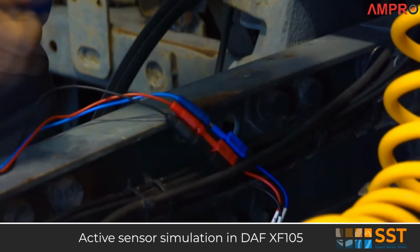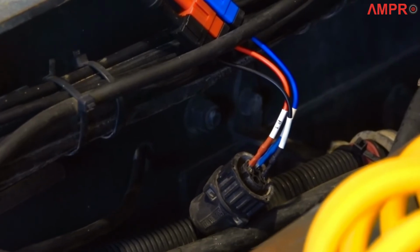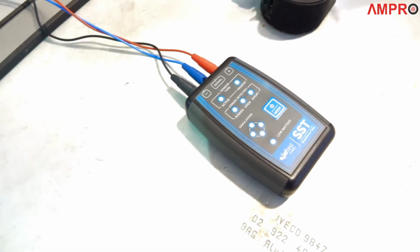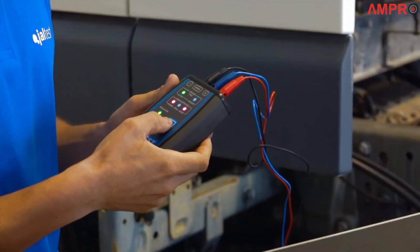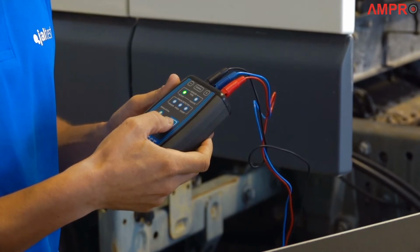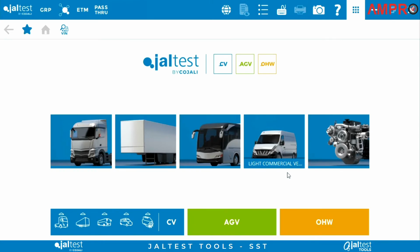To simulate an active sensor signal with Jaltest SST on the control unit, we will need to connect the device to the other side of the speed sensor connection. By connecting Jaltest SST to the control unit and simulating a signal from an active sensor, we can check how the measurement corresponding to the output speed sensor of the gearbox varies its value. In the simulation mode of active sensors, we check whether the control unit is registering correctly the signals that are sent from the SST to the control unit.